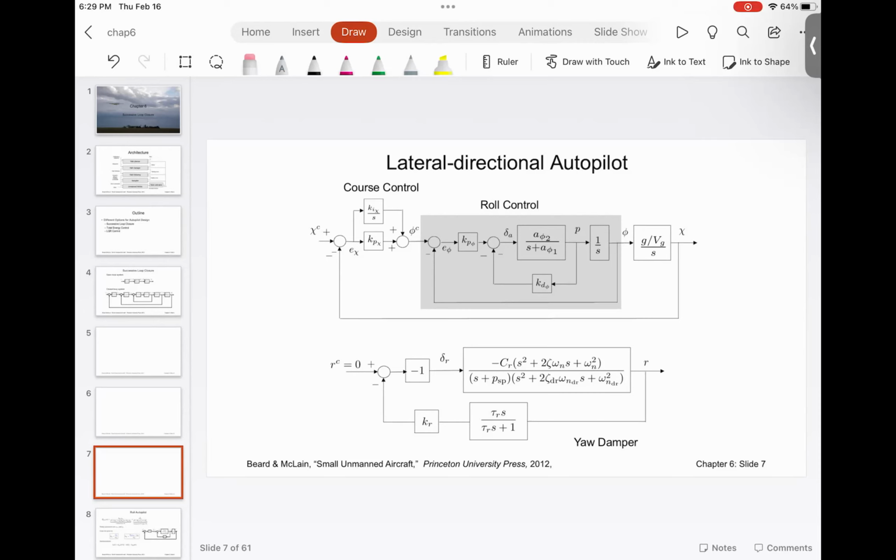and understand, if I increase the damping, the system response kind of dampens. If I increase the stiffness, basically what happens is the natural frequency increases, so you get oscillations like this. What that means, if you have this real axis, and if you have an imaginary axis, if I increase damping, my poles go towards the left-hand side. And if I increase spring stiffness, basically my poles travel in the vertical direction.